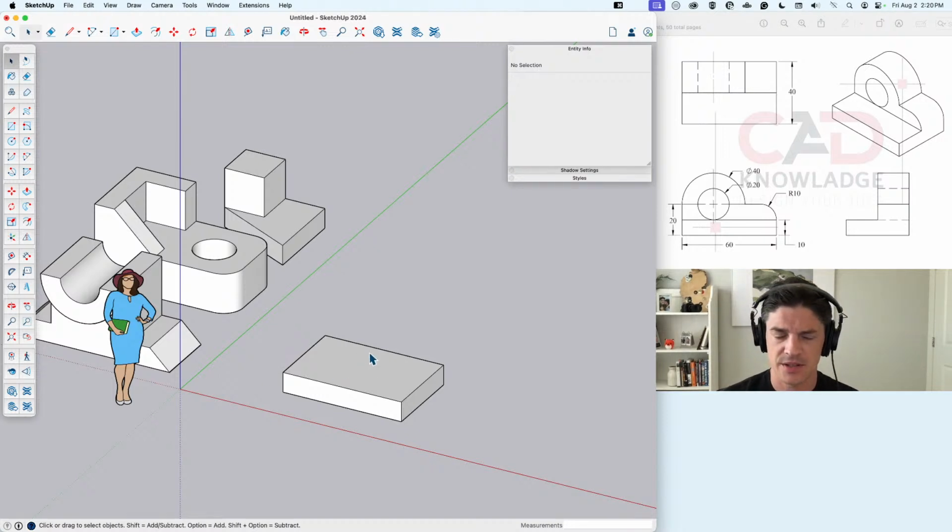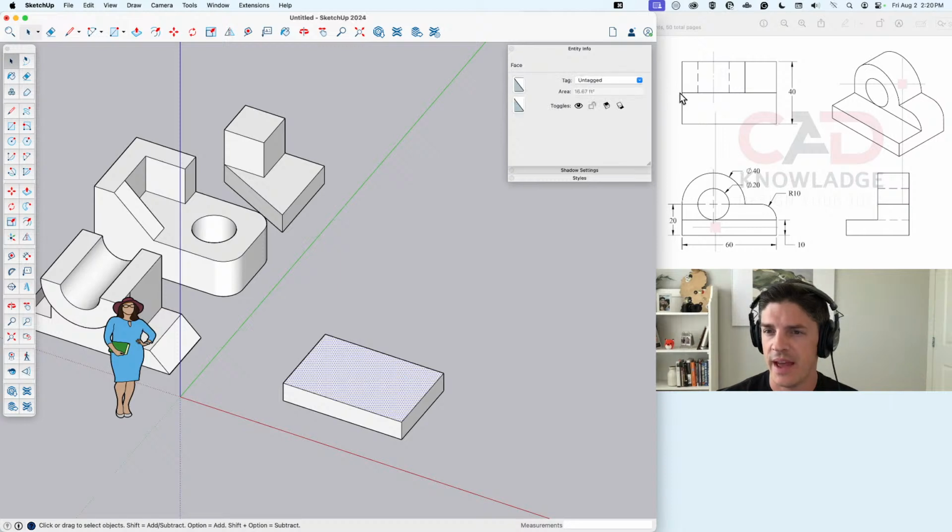I'm like, okay, so is this half? Is this 20 up and another 20? It doesn't really say, right? It looks midpoint though. I mean, if it doesn't specify, the only reason to put two dimensions on it would be if it's not centered. If you show it centered, it's assumed that it's snapped at the midpoint.